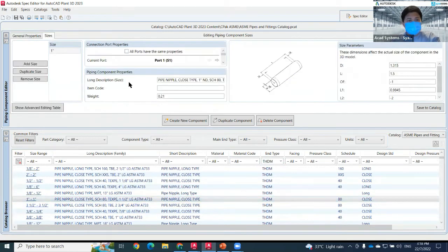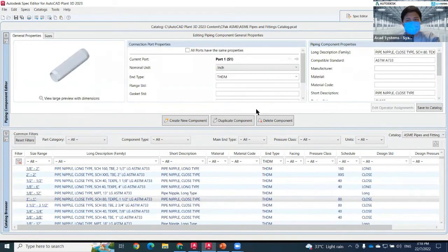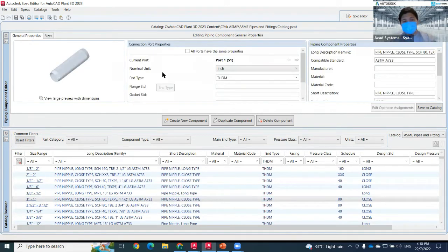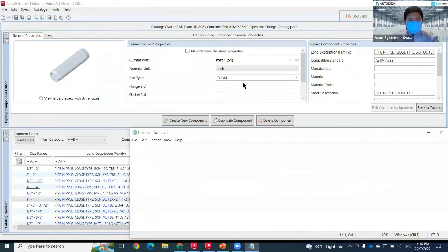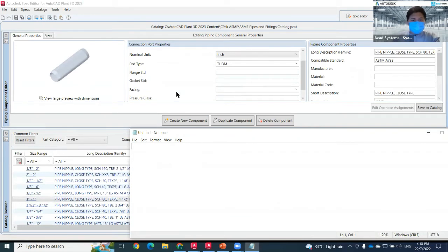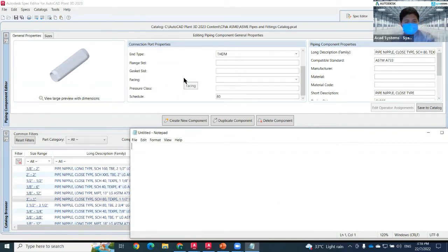Okay, with a nominal diameter here matching OD 1.315. Okay, that will be the information that I need. So not bad. Okay, so pressure class 0. Okay, for piping, no need to insert the pressure class, but if you want to insert, then you can also insert. This one, pressure class should be none for pipe. This one is for pipe, right?